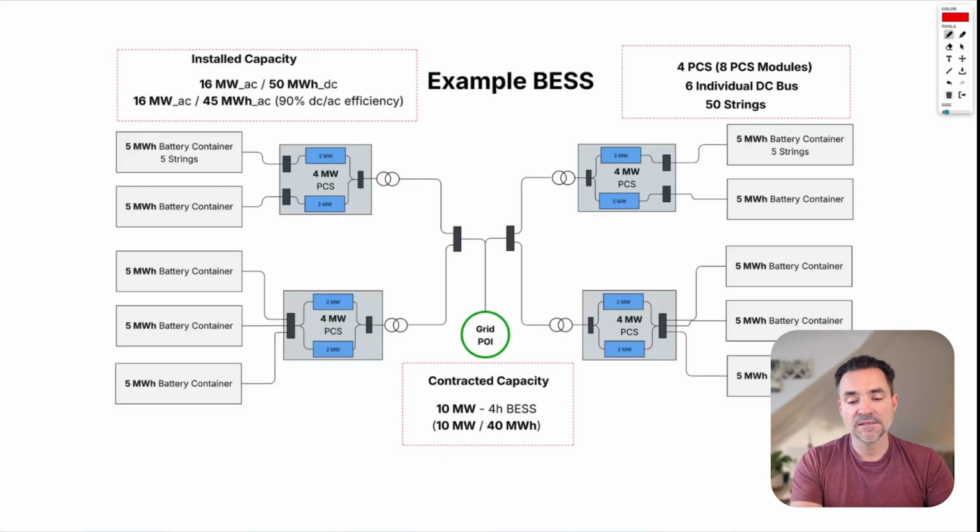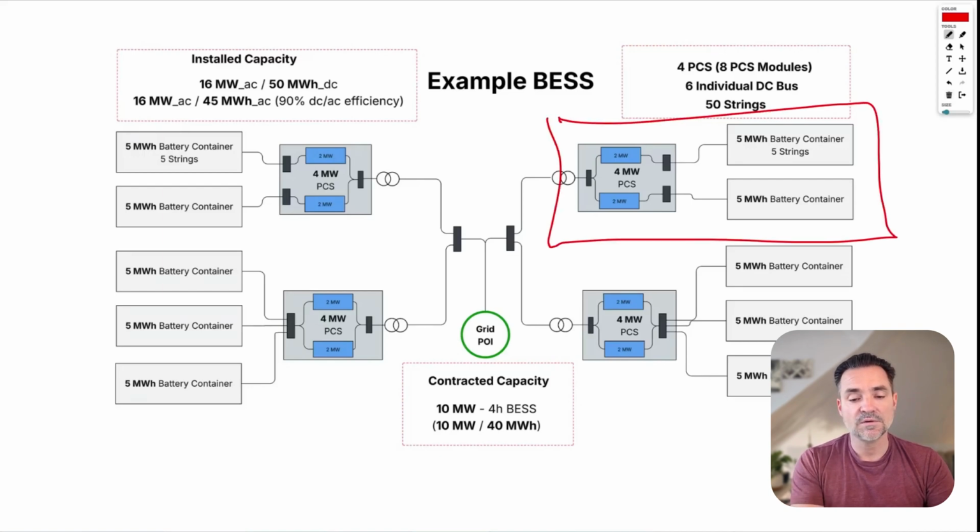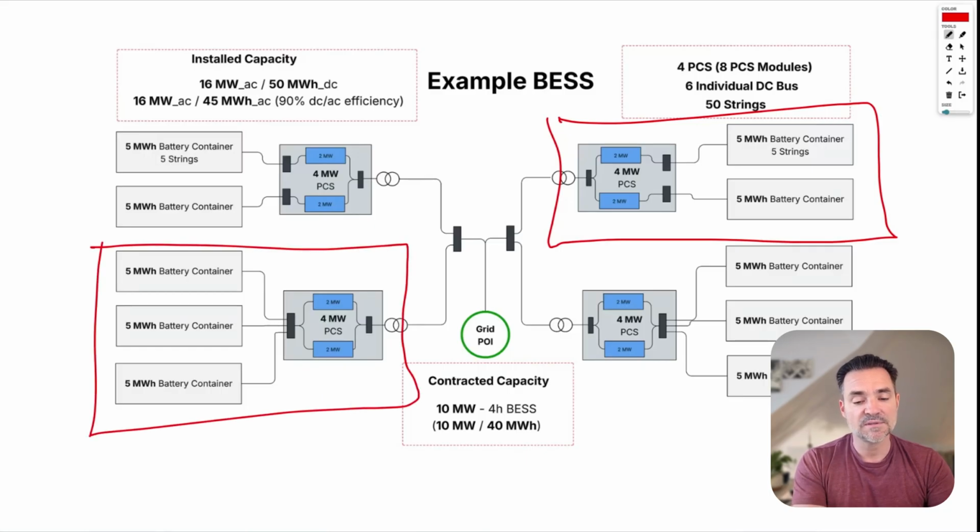And you can see the reason we choose this example is they're not all the same. Some blocks have 2 batteries. The PCS are configured with 2 independent DC buses because they have 2 modules. But some stations have 3 batteries, and because we cannot divide 3 in 2, these stations actually have a single DC bus. This is a pretty typical configuration of a plant.